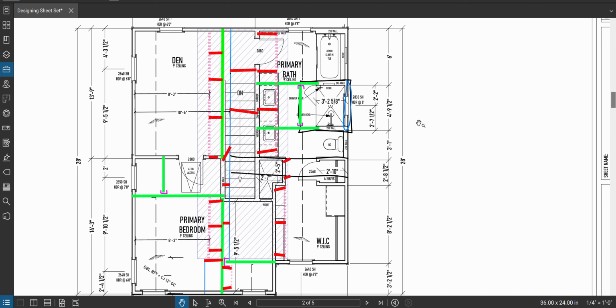The first thing I'm going to do is pick a beam and get started. I'm going to start up high on the top and work my way down through the building. The other thing I need to do is notate where I have concentrated loads going down through my walls so that I can make sure I catch those with either beams or special things.